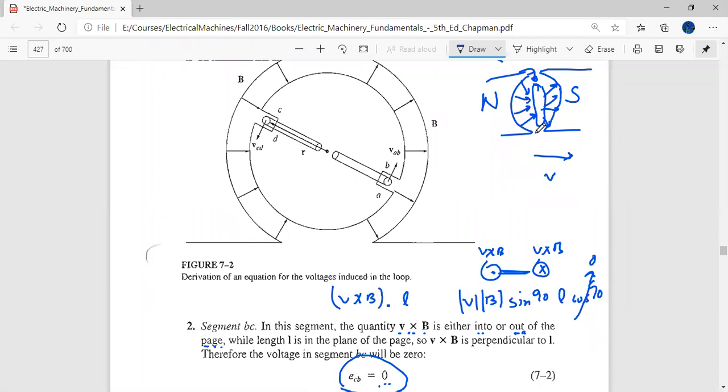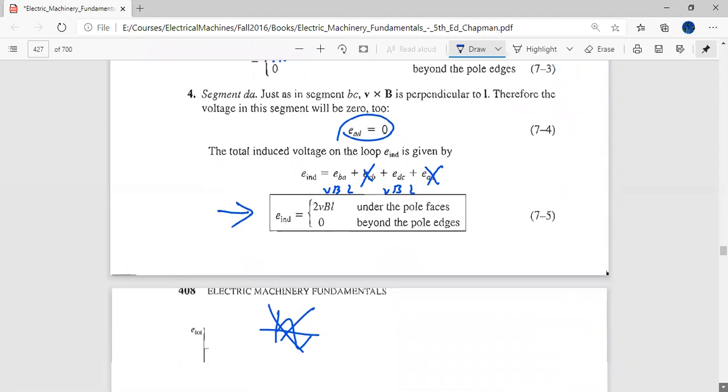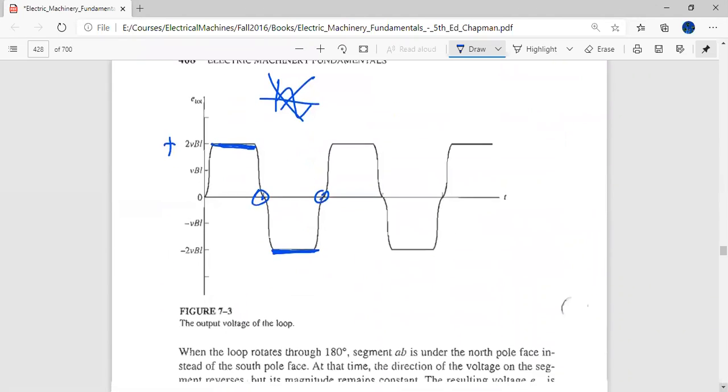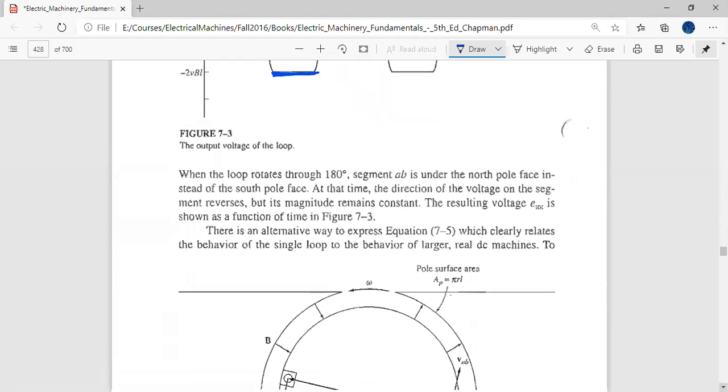Because of the air gap, there is no B field over here, and all the B directions are going radially. So for just this moment, when it doesn't find the field, the induced EMF goes to zero. Just momentarily, when the plane of the coil is perpendicular, it doesn't find the B field, and the EMF goes to zero. Immediately after that, it again receives a perpendicular B field.